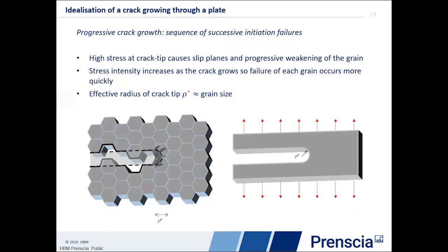Taking this idea, it gives us the ability to predict the stresses in detail in front of and actually back of the crack tip, where historically we've assumed that they were singular and used just empirical rules to do things like crack closure. Now we have the ability to actually track the stresses in front and behind the crack tip and do a more thorough calculation.